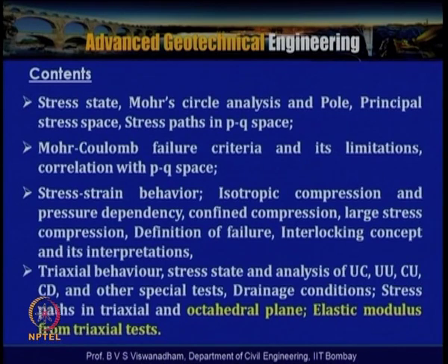Then we discussed the Mohr-Coulomb failure criteria and its limitations, and different stress-strain behaviors under isotropic compression, and definitions of failure and the interlocking concept. Then we introduced triaxial behavior and stress state, particularly with reference to the unconfined compression test, the consolidated undrained triaxial test, the consolidated drained triaxial test, and other special tests. We have not covered the special tests much, and we also discussed the drainage conditions.